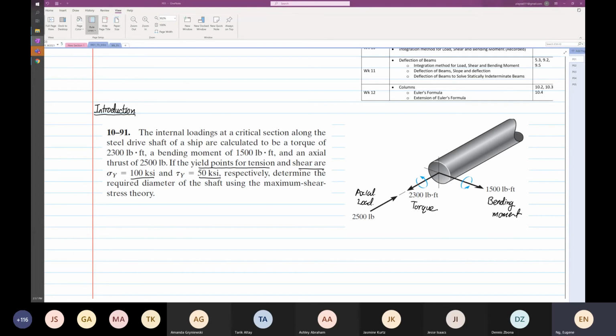Okay, this is the real world. This is 3D stuff. What you'll see are problems like this. There won't be any isolated problems. There are problems where you have a combined axial loading, torque, and what? Bending moment. Okay, so first of all, whatever things we do, we need to have a transformation. So any problem set that you see, you're going to draw a transformation first.